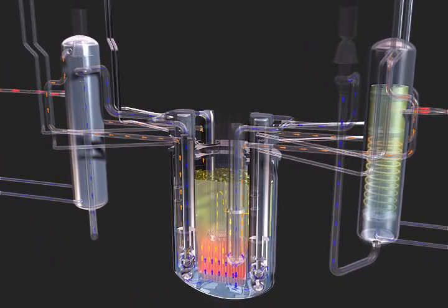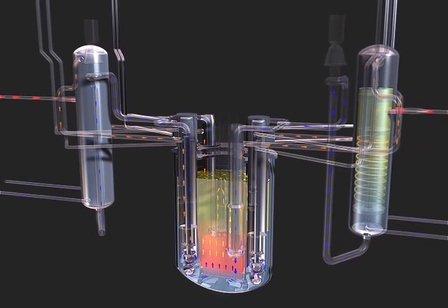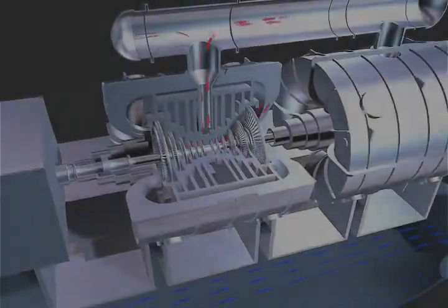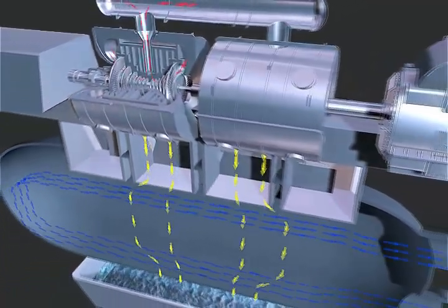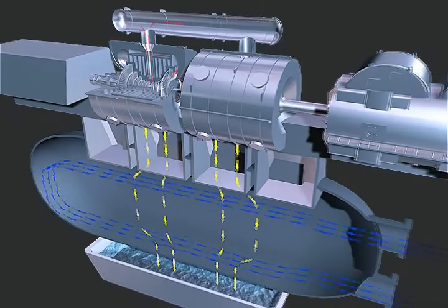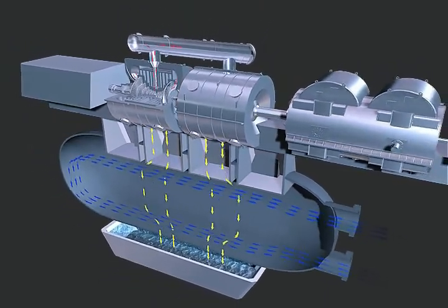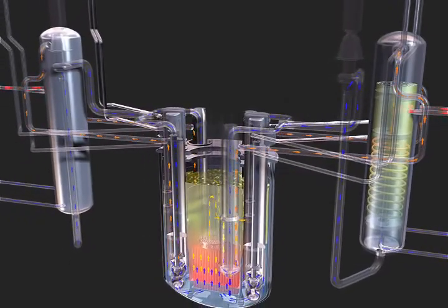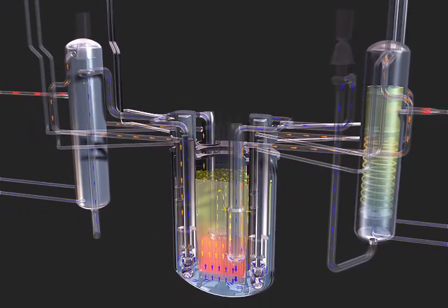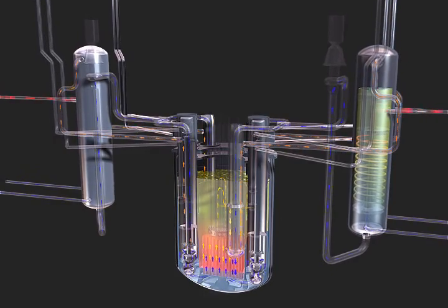The produced steam moves successfully to the auxiliary building and rotates the turbine generator to produce electricity. After this process, steam is converted into subcooled water at the condenser unit, and it returns to steam generators by the feed water pumps. The Korean sodium-cooled fast reactor system has been designed by employing highly reliable and safe features.